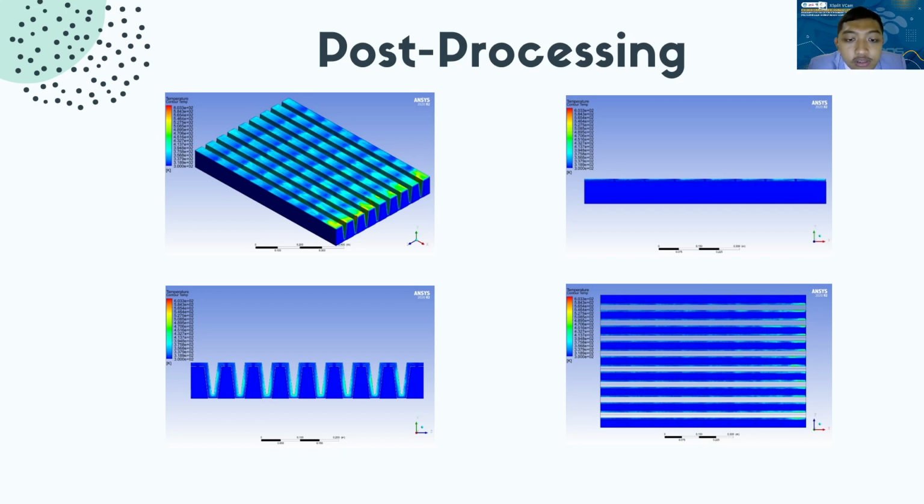If there is no further jet impingement underneath, then the air temperature in the space between the absorber plate and the jet plate will increase again in the range of 337 Kelvin to 375 Kelvin, especially in the area close to the boundary condition on the heat wall side.